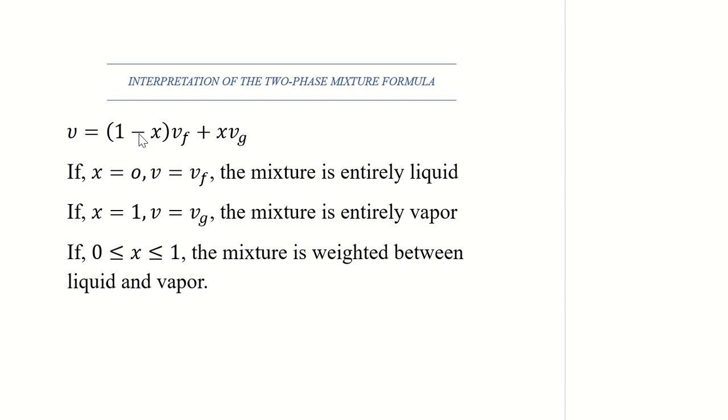So having that at the back of our minds, once you're dealing with calculations in thermodynamics, and you find that the quality concept is equal to 0, once you do the solving here, 1 minus 0 is 1, 1 multiplied by lowercase v subscript f. You're going to remain with this here, and because of this 0, this is going to cancel out. So that means your specific volume is equal to the specific volume due to the liquid phase.